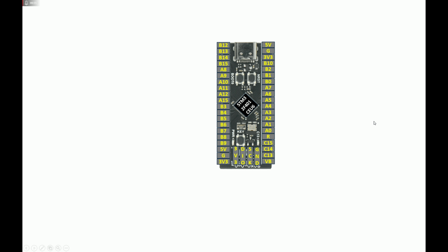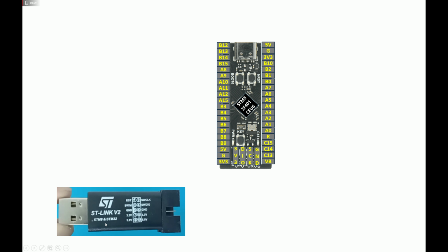Now to program this, unlike the PIC or Arduino, here we use this ST-Link, this small device. It's very cheap and works with nearly all the STM microcontrollers. Now you have to get this device first, then you can see the device is labeled. This labeling is different, and pin configuration may differ between versions of the device, so you should just look at the labeling.